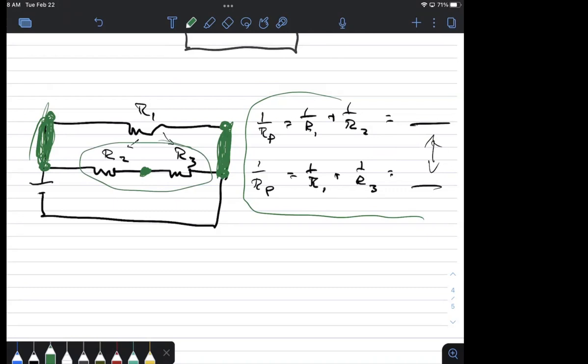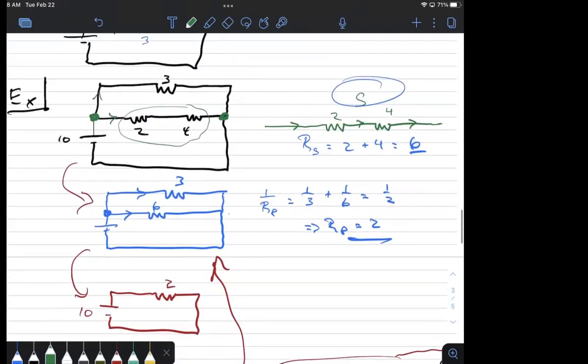And now look at what you have. And it's then easy to go to the parallel, the next simplest thing. Don't try to go with the most complicated, which is, how do I combine R1 and R2 together? Oh my God, that's way more complicated. Just do R2 and R3 and you're fine. Because from there, when you redraw it, the thing you redraw is simple too. It's just this little parallel guy. And I can do parallel, that's easy.